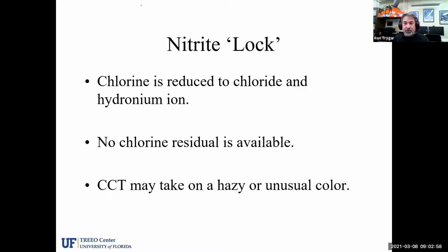I just want to point out one thing here, that in most of our manuals we're finding that the ratio of chlorine to nitrite is something like this. It's generally about 5 milligrams of chlorine, of HOCl, to 1 milligram per liter of NO2 to be oxidized.